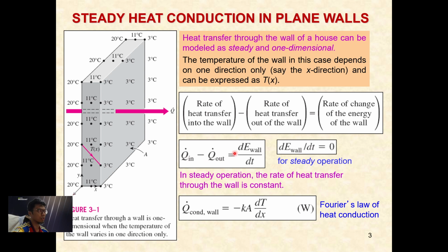Okay, so it is simple. So we know that the heat transfer rate from the hottest part is equal to the heat transfer at the outer part on the other side. Okay, since we are studying only steady state operation, which has no time involved, Q in equal to Q out.